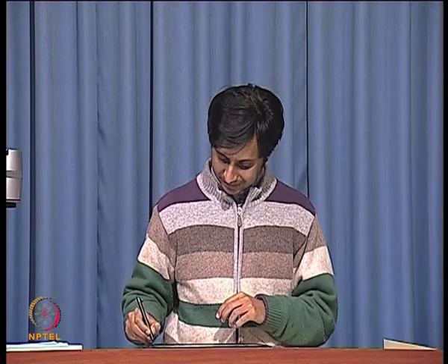Okay. So, these class D amplifiers are not commonly seen in cell phones. Primarily the problem is the pulse width modulated waveform that you need at the input of the class D amplifier. So, that is a big stumbling block, especially when you are talking about extremely high frequencies. However, the class D amplifier is very popular at audio frequencies.